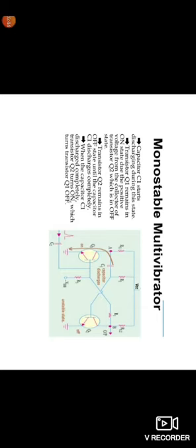Here there are four steps. The capacitor C1 starts discharging during this state. Transistor Q1 remains in on state due to the positive voltage from the collector of transistor Q2. Q2 remains in on state because VCC is applied, so the current moves through RL2. There is a voltage drop. Q2 off means there is no current movement towards the transistor Q2.